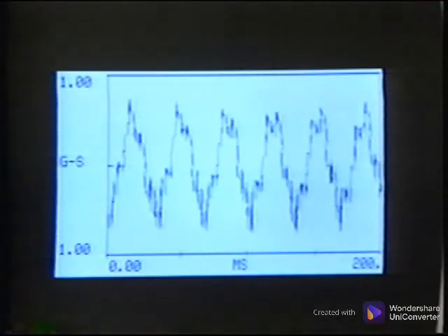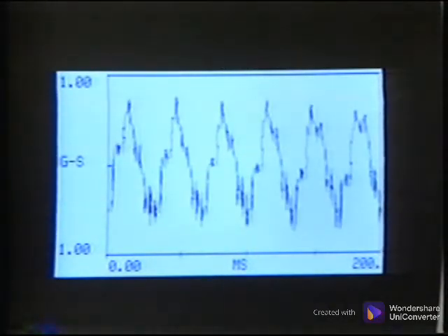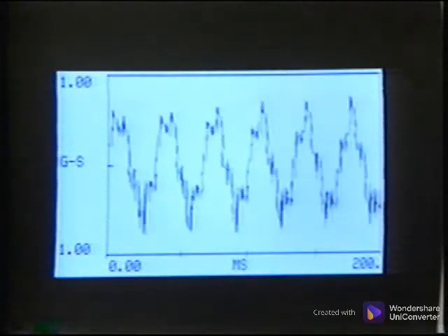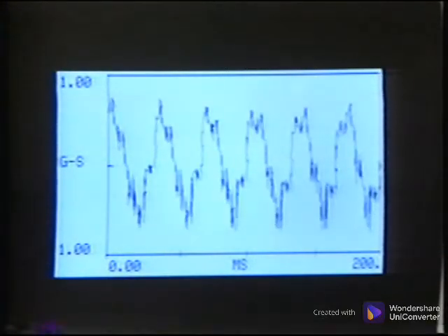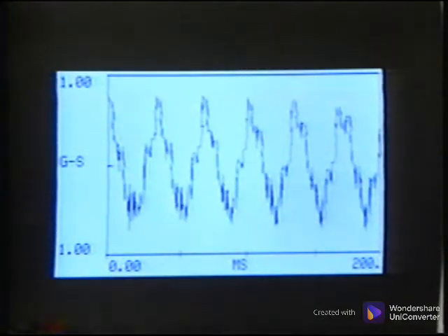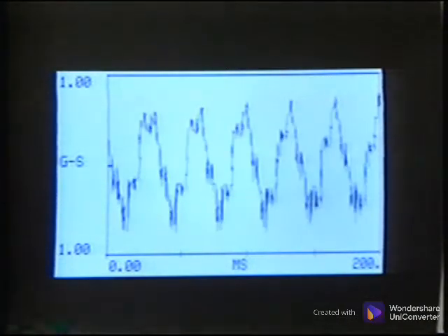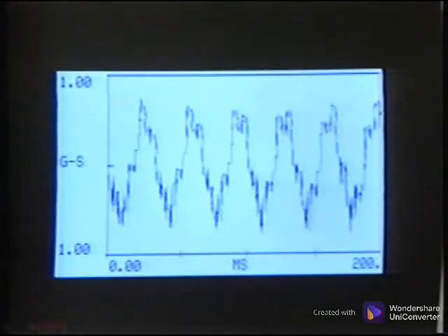The waveform in acceleration units is more complex due to the energy from high-frequency impacting riding on the 1 times sine wave due to the unbalance. But the waveform is still dominated by the single frequency due to the unbalance.